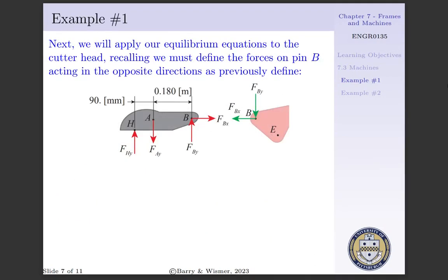Next, we'll apply our equilibrium equations to the cutter head, and we will recall that we must define the forces acting on pin B on the cutter head acting in the opposite directions as previously defined on our handle. This is shown in the figure to the left.